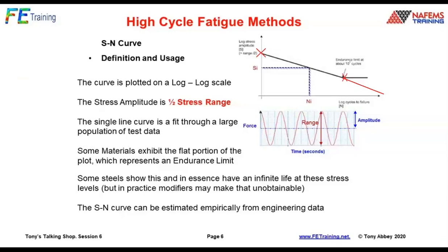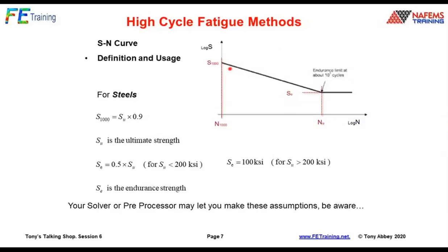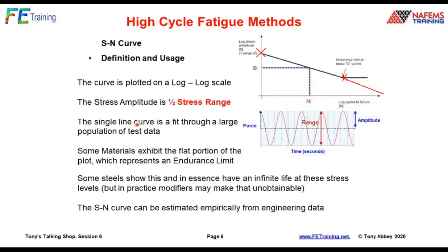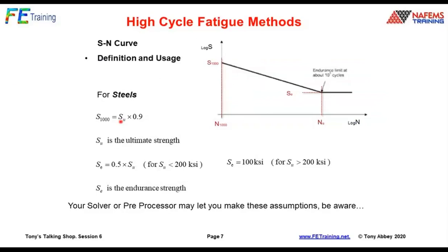So those are the two ranges of stress at which we're drawing the graph, which is perhaps a little bit confusing. This is the S-N, high cycle fatigue graph, and now we've got an interception point which is actually a very, very high stress level. So this is the S-N curve. We need to have two sets of data there to describe the curve. I haven't put them on this graph here yet.